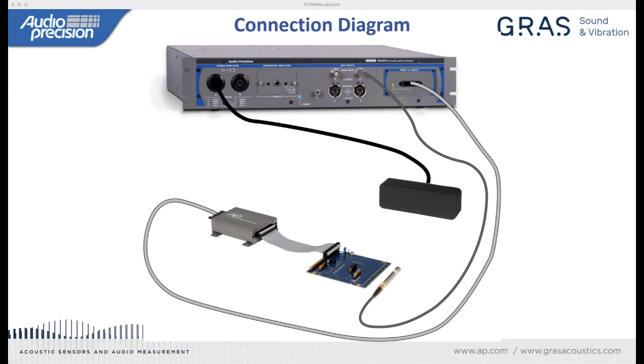But in this particular case, I would say that the main downside for microphone measurement purposes of a 1/4-inch microphone is its self-noise and its sensitivity, which are not going to be optimal if I want to establish the ambient noise environment, or measure distortion on a microphone. But the fact that it's small and doesn't interfere with the sound field as much is very handy, regardless of the type of microphone I'm measuring.